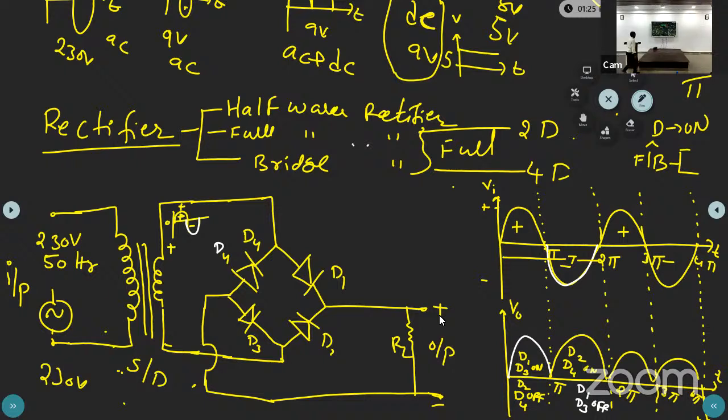Okay, there is a bridge rectifier output. Now the output of the rectifier is this. This rectifier output, we are connecting to the filter input, the continuation. So we constructed the bridge rectifier, and the bridge rectifier output we are deriving. So we got the pulsating DC. This DC has AC plus DC, the two parts: the AC part is present and the DC part also.